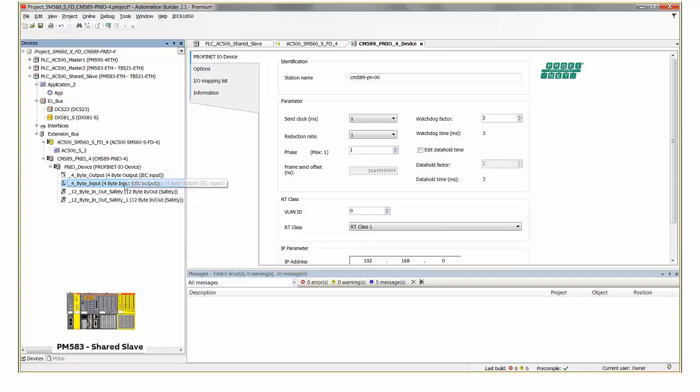And then we have 2 safety communication modules. One is from master 2, again some predefined counter value, which we want to visualize on our DX581S module on the shared slave. And then the second one is to transfer this value further to the master 1 system, again to visualize it using LEDs on safety digital outputs.